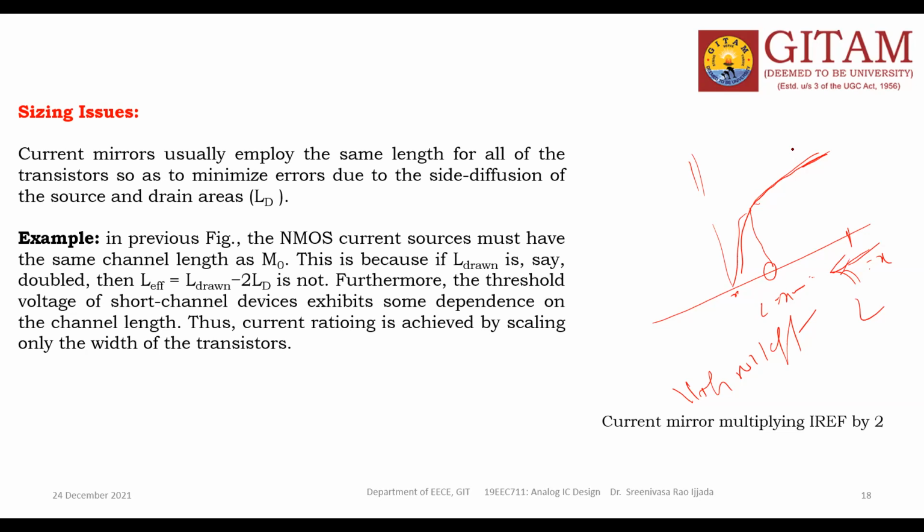That is the issue. So you have a ratio between the subthreshold current and the VTH value. When the VTH value is small, the subthreshold current is large. Sorry, they have an exponential relationship, e to the power of minus VTH. So don't touch the length, because this is the problem.